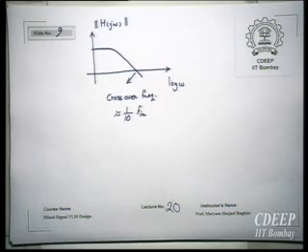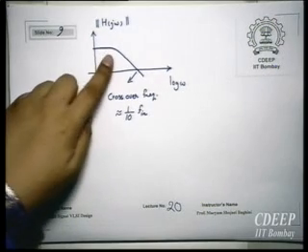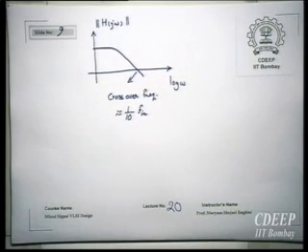Therefore, definitely this should be below that. Of course, this is megahertz. Usually the input frequency is in the range of kilohertz if it is coming from a crystal. Megahertz is very difficult to develop. But anyway, it should be 1/10 of that. And then you design the filter in such a way. Now you know this is the crossover frequency you want, now you decide about the location of the pole, decide about zeta. It's an iterative thing. So this is in fact the main rule of thumb for the design.